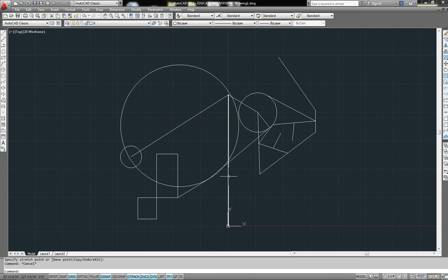That pretty much wraps up this tutorial on drawing lines and shapes and using the object snap commands. Just remember, when you're using the line commands, always make sure your units are architectural units, and make sure that you use the foot symbol if you want to enter some dimensions in feet. If not, any numbers you specify will be assumed to be in inches.